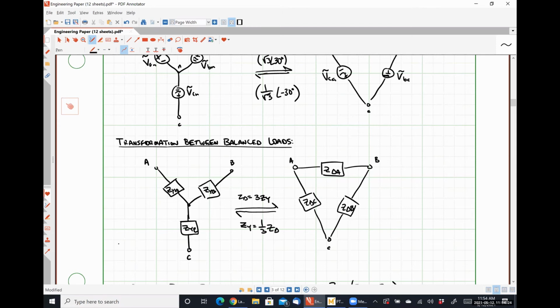In an HVAC system, you have a compressor, which is typically three-phase, and then you have a fan blower motor and a fan intake motor, which are typically single-phase. So you have an unbalanced system inherently, because you have a balanced three-phase system connected to two single-phase systems, which are going to put the system into imbalance.